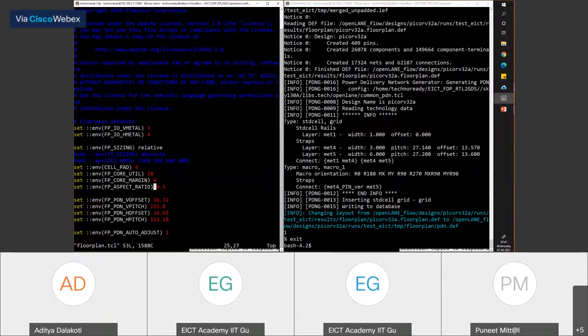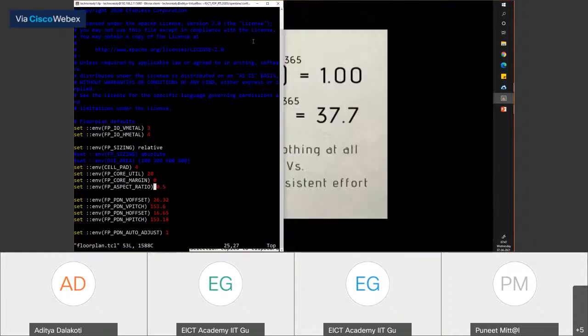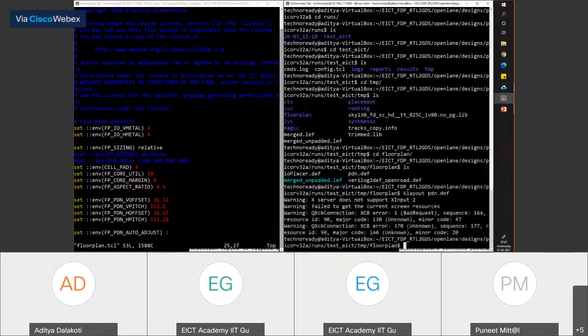Okay, I'll let you guys run this. Run floor plan, yes, it runs PDN, Gen PDN, but it doesn't run, evidently, tap decap, or you need to still run tap decap, or it might just be not running it on my end. You can check. It tells you where the design is saved, what all did it run. It all gives it in the log file. So please run this at your end. I'll give you 5 more minutes, and then there are some closing thoughts I want to leave with. We'll discuss some other concepts, and then we'll call it a session today.